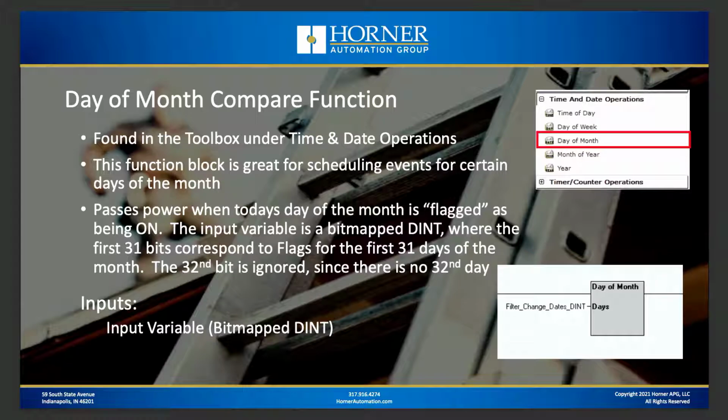However, I wanted to cover this day of month compare function again because it's a really useful function for anything that you want to have happen from a scheduling standpoint based on a certain day of the month. I'm not talking about Monday, Tuesday, Wednesday. I'm talking like on the 7th and the 21st or the 14th and the 28th, that sort of thing.